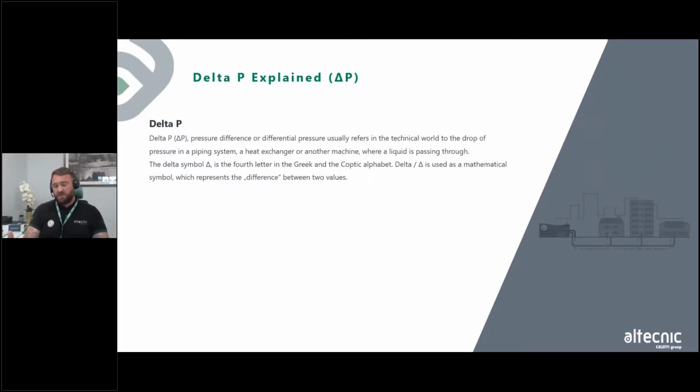And the way to do it is what we call an index point. So we want to know that the furthest HIU on our system is going to get enough energy. If the minimum is 35 kPa and the maximum 165, and you set your furthest HIU on the system for the pumps to reach out at 50 kPa, you'll know you've got a 15 kPa band or difference there to play with, but the furthest HIU is going to get enough energy. Then as you come back towards the energy center, you're going to have enough energy without going too high, to make sure that every HIU has got the correct energy going into it.